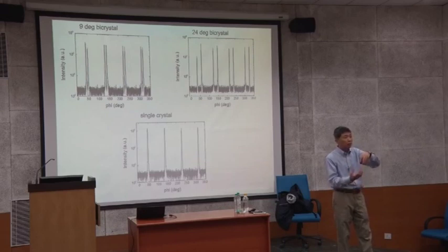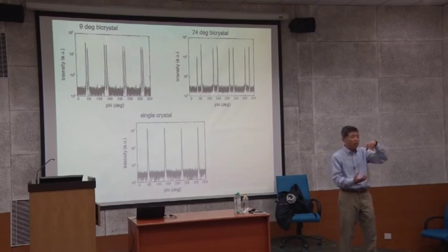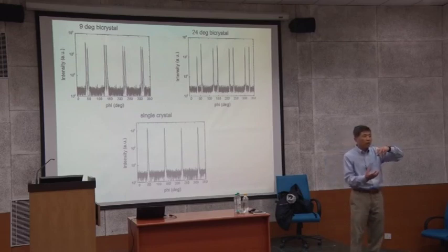You want to measure the strain relationship. And then when you grow this, is your crystalline quality good or bad? Good crystalline quality is measured by rocking curves and out-of-plane scans. Or you grow this and it's really single crystal, or a bicrystal, or you grow some multi-domain crystals. You want to determine this, and you get the size or thickness distribution. All these things you can get from this diffraction work.